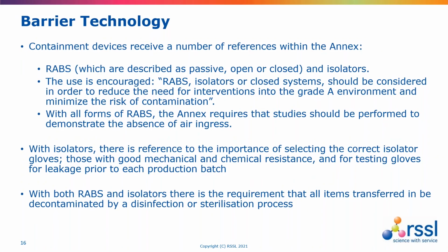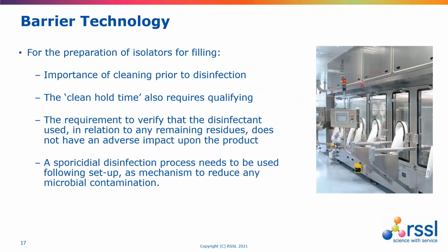There's also an important emphasis upon assessing isolators and particularly the individual glove ports for leakage as representing key weak points.